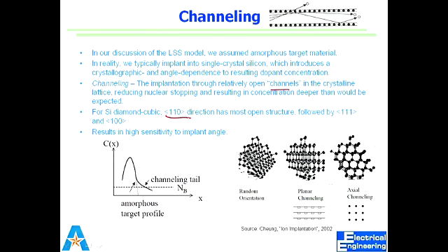But in dry oxidation, it would make a difference, right? So not just the process, the end product would also be different based on orientation. So this is another process which has some non-ideality that differs with orientation.